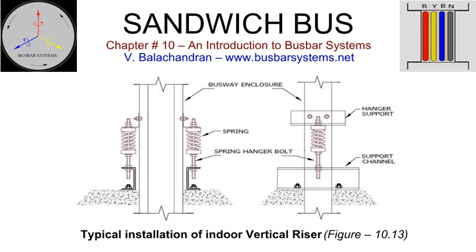Typical installation of indoor vertical riser in a high-rise building. Spring-loaded supports ensure that the weight of the busways is shared equally by all the floors and caters to the thermal expansion.